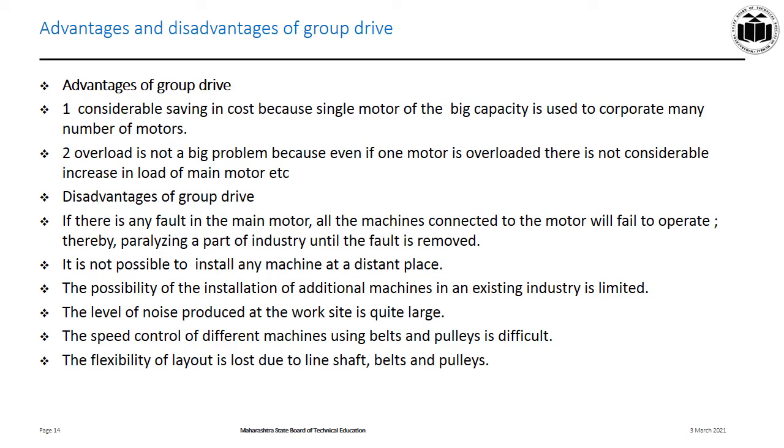Advantages: since a big motor is running a number of systems, it is quite beneficial and quite cheap, and it doesn't give the overload problem. But a few disadvantages are associated with the group drive: if there is any fault in the main motor, the full system will collapse.